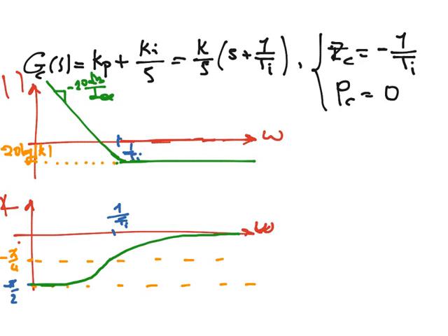Okay, now let's see how we can manipulate the Bode plot of the overall system in order to obtain the required characteristics for the system. As I already mentioned, we want to manipulate the low frequency behavior, and we want to keep the high frequency behavior similar to the original case.